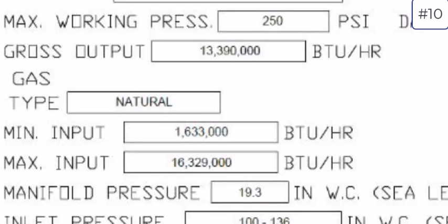And what we're looking for with a condensing boiler is an ability for the boiler, through its heat exchanger design, to extract extra energy out of the latent heat of vaporization by condensing water vapor out of the flue gases, and that phase change process puts extra energy into the hot water, assuming that you have return water cool enough, meaning that the return temperature, or the inlet to the boiler, that water temperature is below the dew point of the flue gases to be able to achieve that phase change and condense the water onto the surface of that heat exchanger.